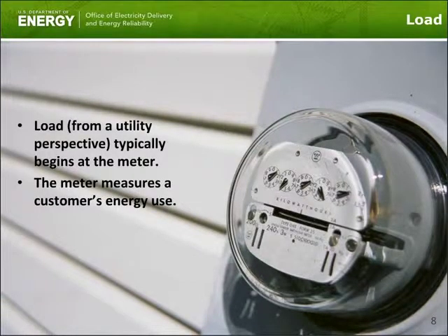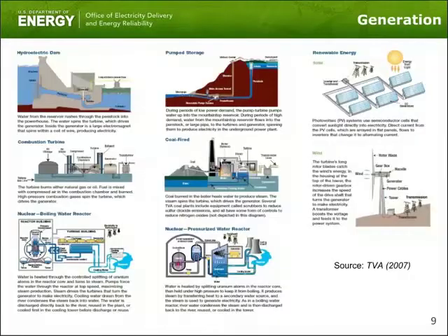There are 2 different types of loads, and those are resistive loads and inductive loads. Resistive loads are typically things like what had been the incandescent lighting, the heaters, like your oven or your toaster. And the inductive loads tend to be things that have motors, magnetic fields. Those are your compressors, your pumps, your fans, household appliances like washers, etc. And the grid has to be able to meet all those different load characteristics and do so in a reliable and affordable way. Slide 9, please.